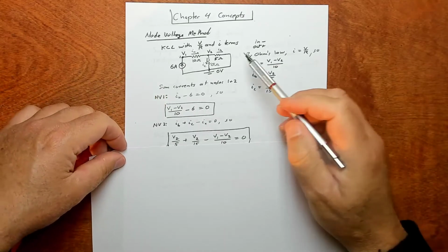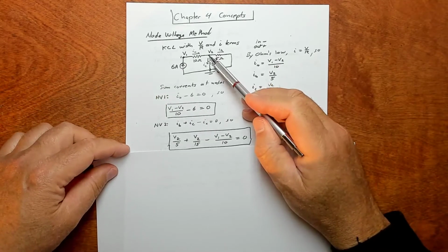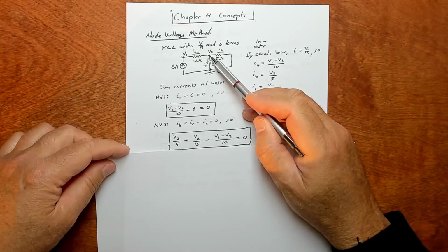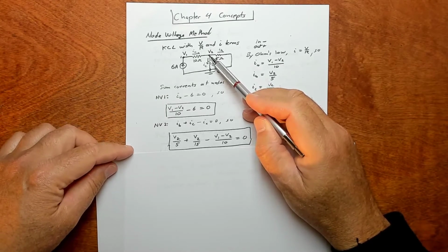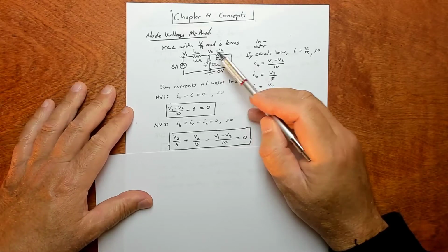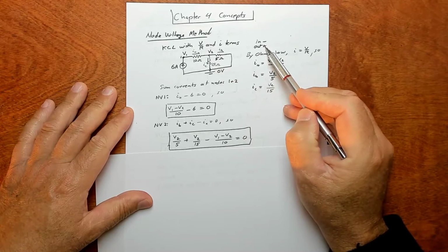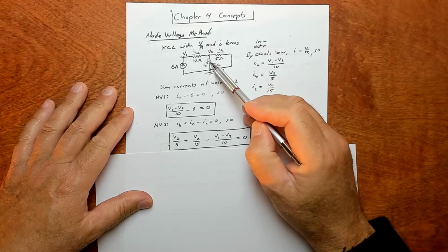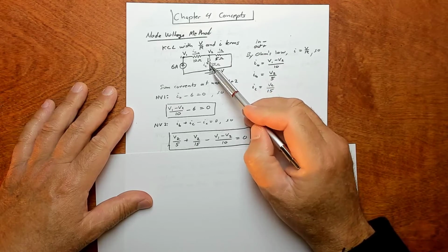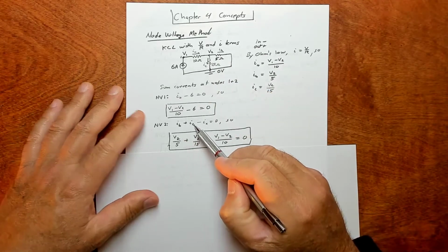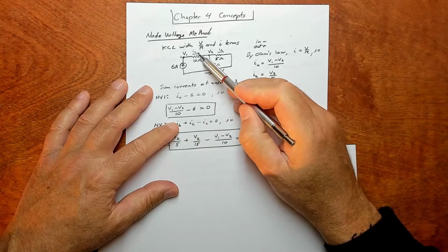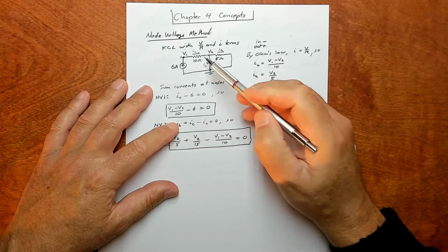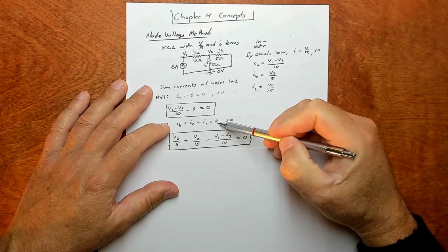All right, now we have another node. We have the second node, so we can do a node voltage equation for the second node. That is, we'll apply KCL at this second node. So currents going out are positive, currents going in are negative. So I have IB and IC going out of this node, right? They're leaving. So IB plus IC, you write. And then I've got IA coming into this node. So that's going to be negative, and those sum to 0.